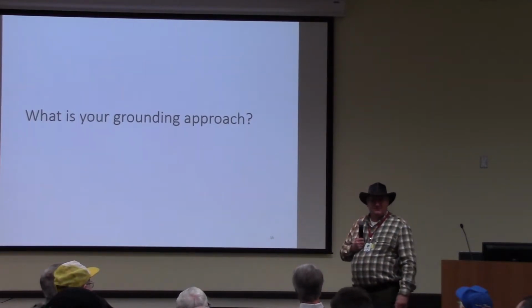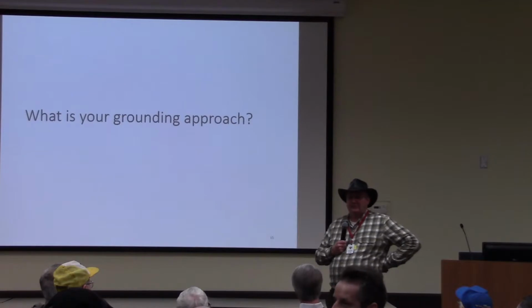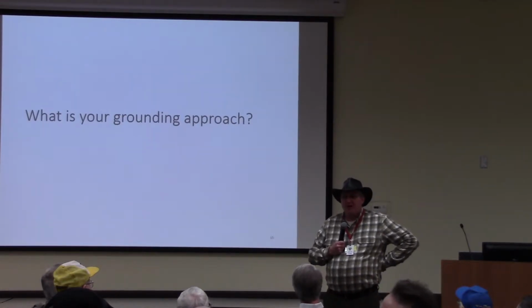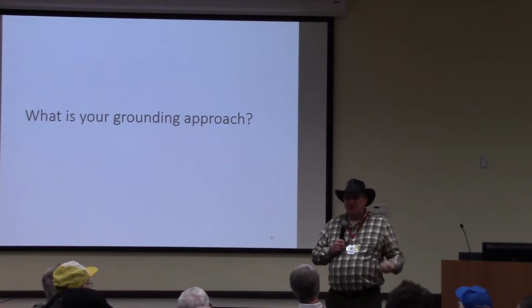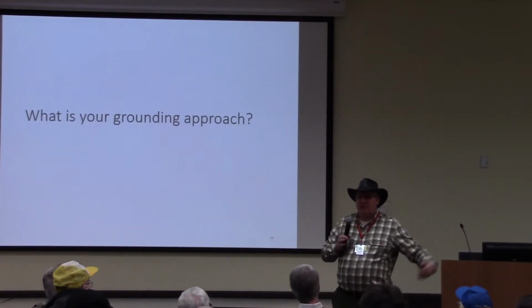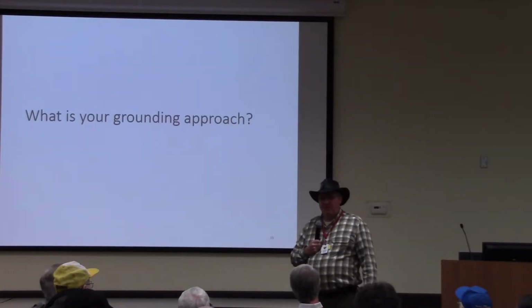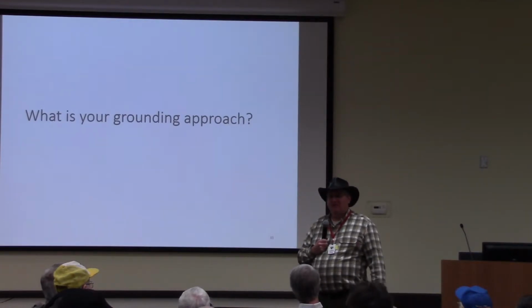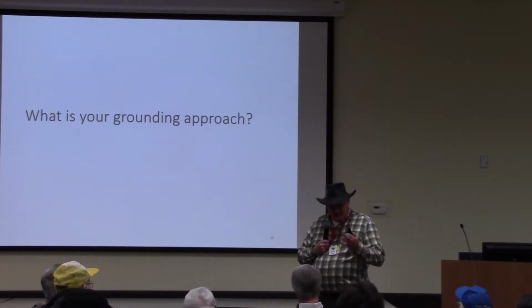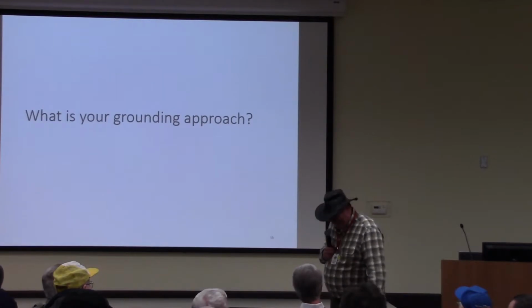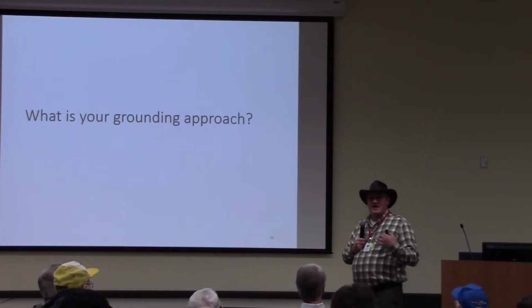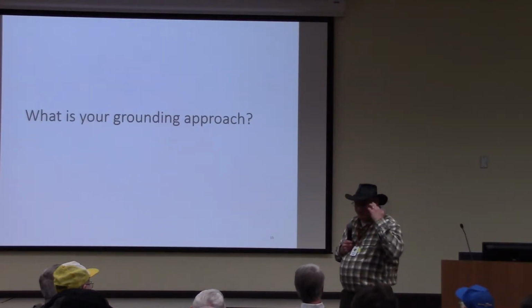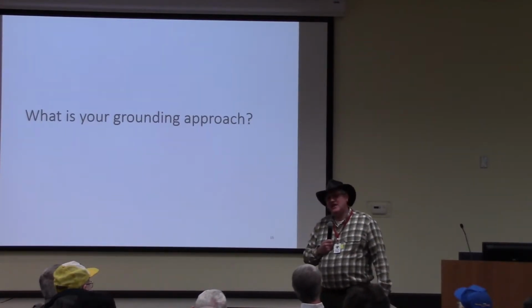I've heard of people who put them in glass jars or jars full of marbles. Yeah. All that's doing is trying to increase the dielectric, which means, in simple terms, they're trying to make it appear to be further away. Does it work? It depends. It depends on how many marbles. It depends on the contamination. It also depends on the contamination on the surface of the marble.